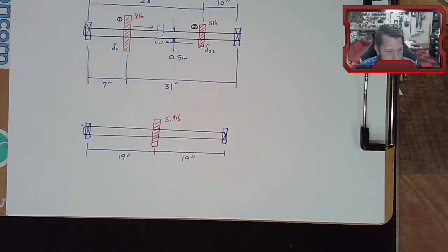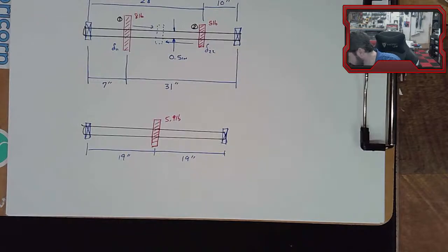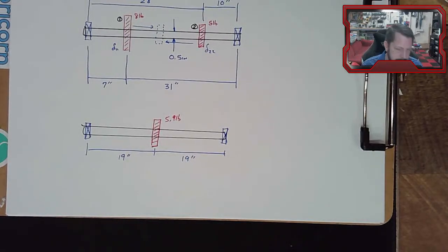But there is a guideline. I don't know exactly where it states it, but just like in the springs, where we were supposed to be 15 to 20 times lower than the critical frequency, for shafts we only have to be half as low.